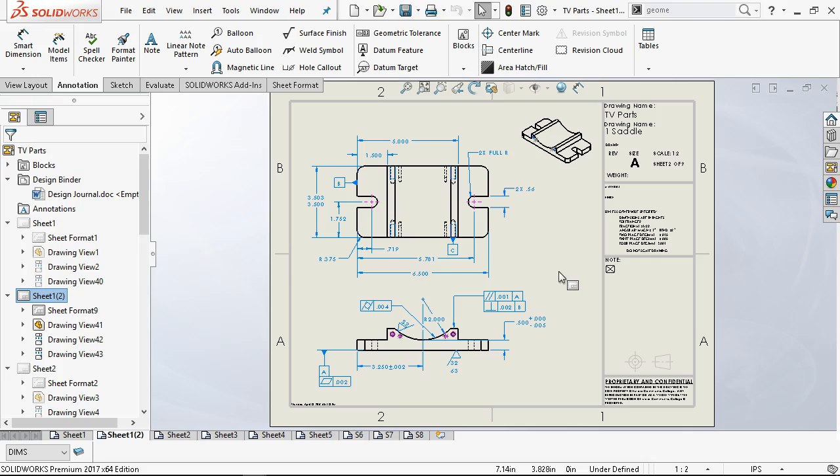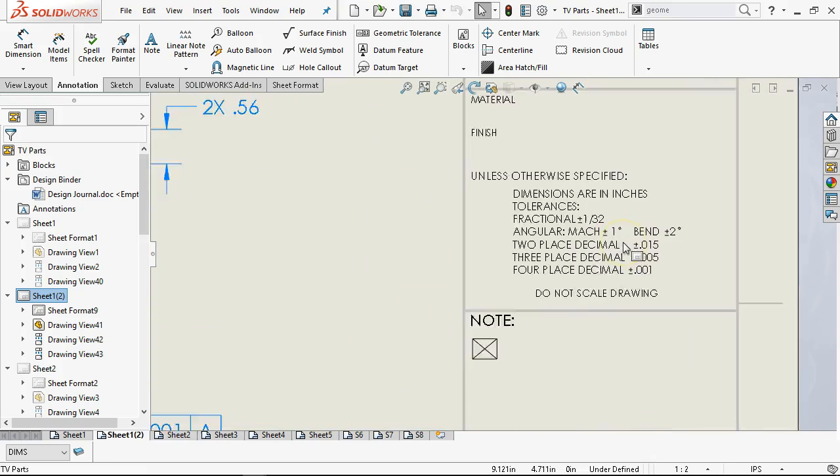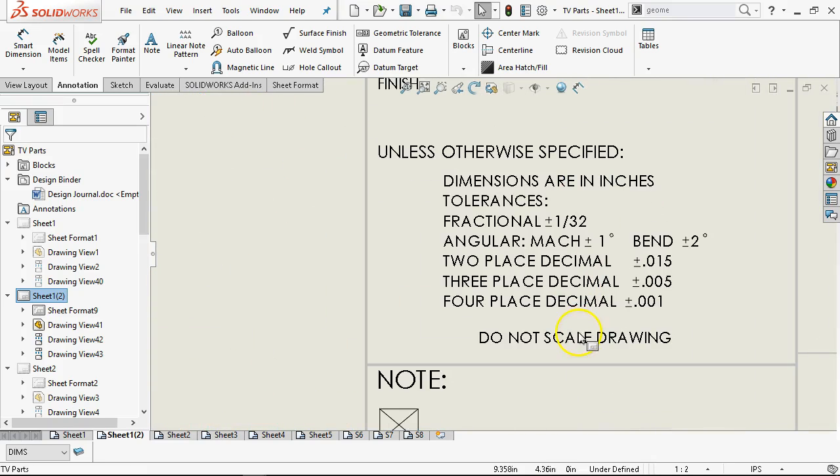We talked a little bit last time that our standard tolerances were pretty much what we had put over in the title block. Plus or minus 15 thousandths. Some places maybe plus or minus 30 thousandths. Some places, if we're in the woods and construction, plus or minus 60, plus or minus 1/8 of an inch.